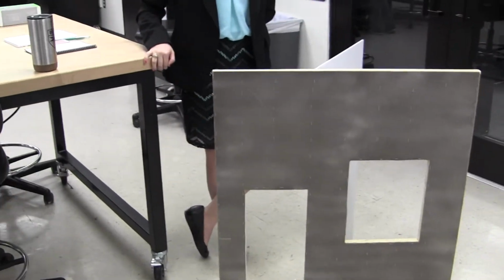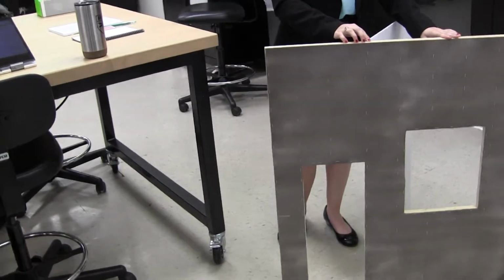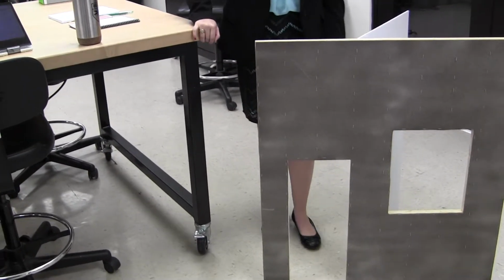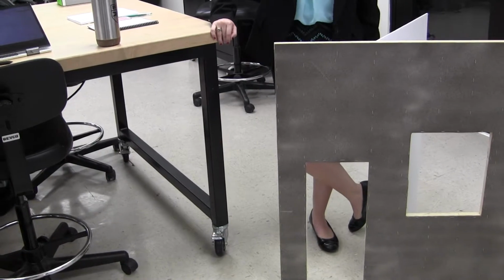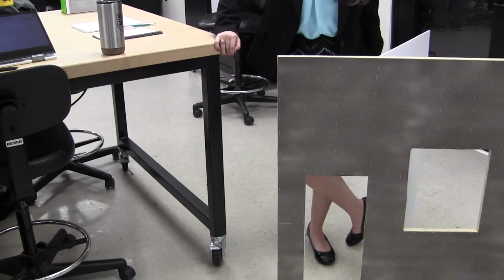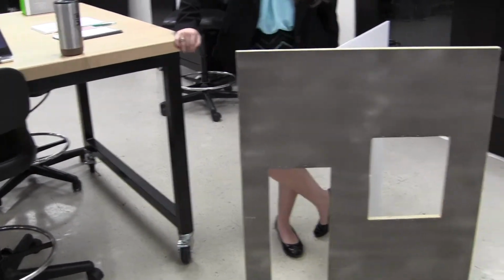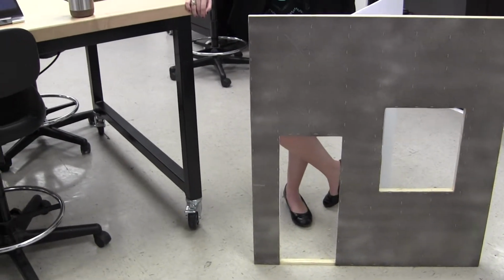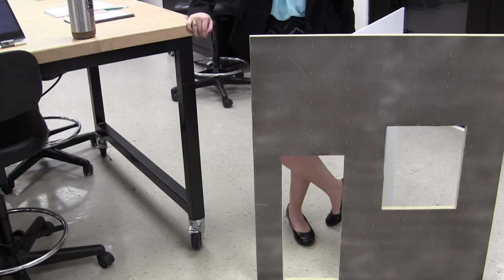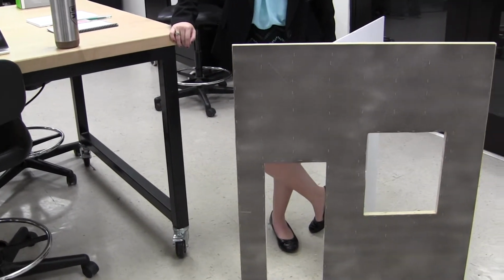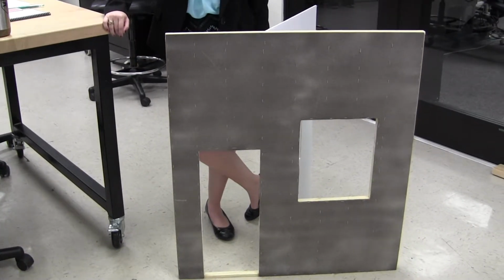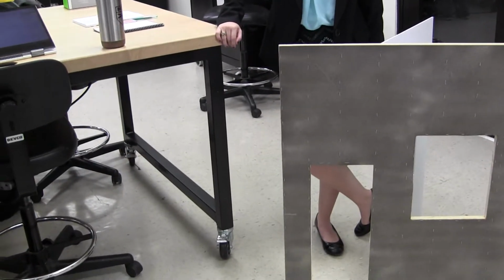You know what you could do that would give it a stucco appearance? It's pretty easy to do with a roller. Do like wall texturing, where you plaster it on. You'll need to put a sealer paint on it, like a brush-on, for it to grab onto, because it won't grab very well onto the little board that you've got. But they do it just like you're texturing a wall of a house.